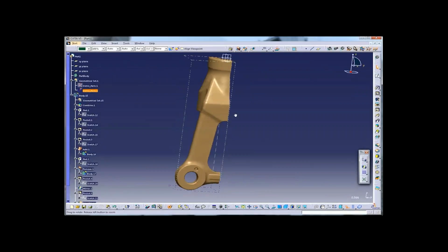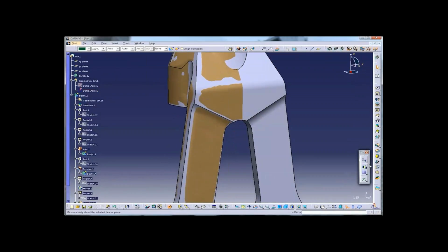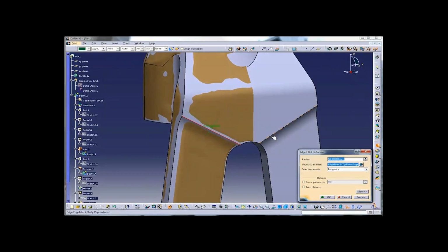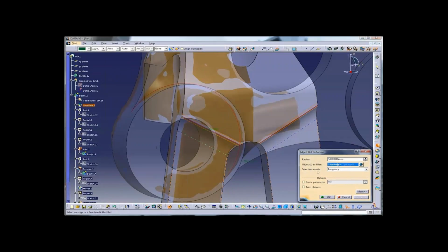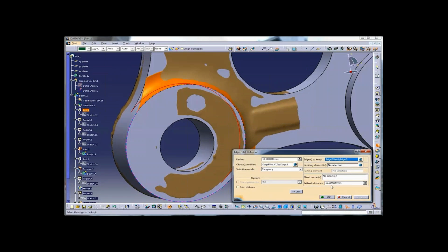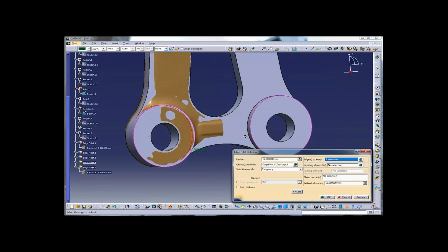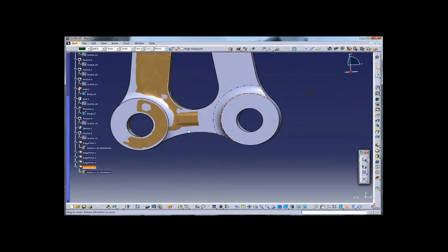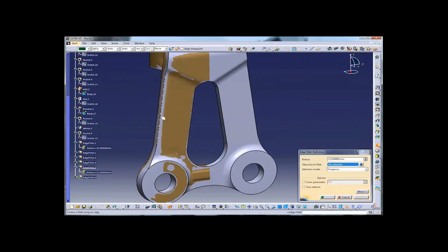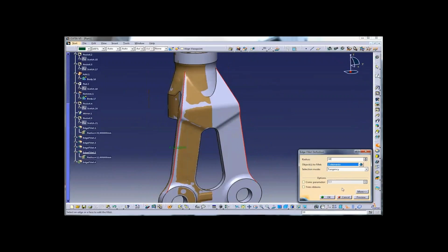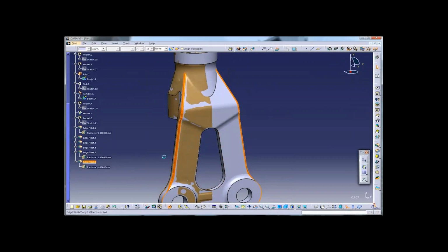So for this part, it's going to take some time. You can also hide our CAD model, take a look at the mesh, do some modification. You can also go back to existing parametric features. So if something is not what you were expecting, well, you can go back to these features and change their dimensions, their profiles, or anything about it, as a matter of fact.